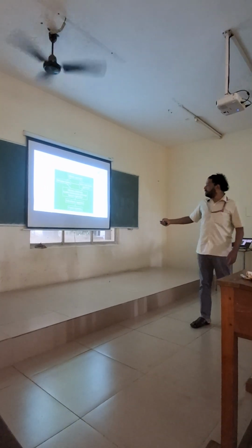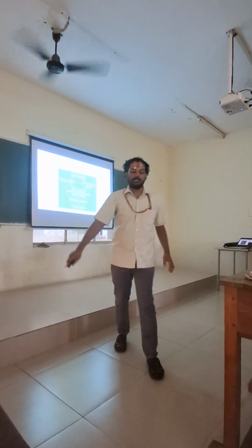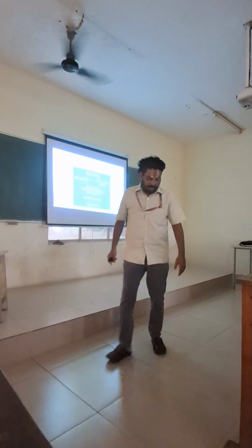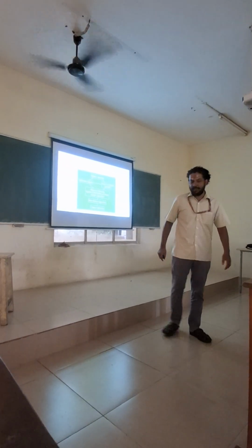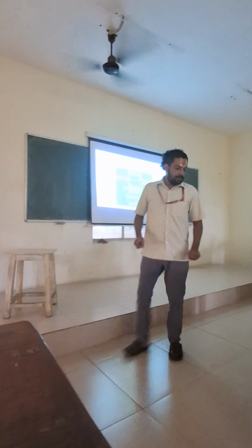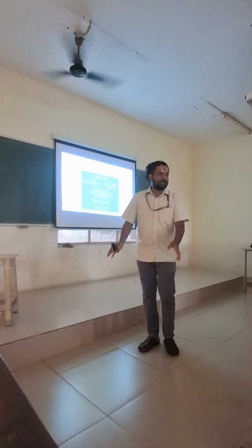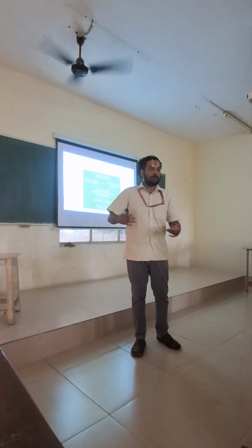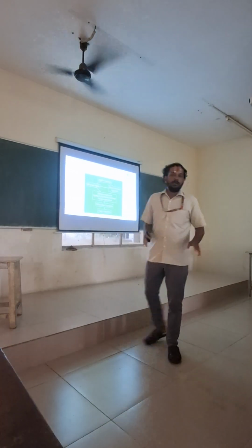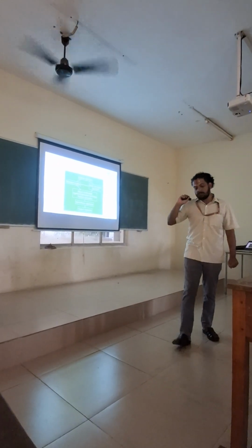The next level abstraction is a drift diffusion approach. Let's say that this tile is actually my lattice. I am an electron. I'm traveling through the tile. I'm traveling through the lattice. Every single point on the tile is a location of an atom. So I'm going to sense, once I start moving, some kind of potential. That potential is going to obstruct or make me scatter and make me move in a different direction. Those things are solved by the drift diffusion equations.